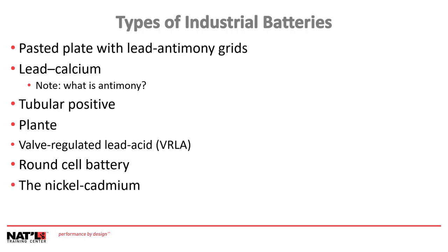Finally, we have the nickel cadmium battery. It is constructed with pocket plate cells for switchgear applications. The battery plates have three different construction thicknesses. Medium or thin plate construction is used for switchgear applications. The maintenance of the nickel cadmium battery is less than the maintenance for the lead acid. Its low temperature discharge currents are higher and it can be charged more rapidly than lead acid batteries. The cost of nickel cadmium batteries is higher than lead acid batteries.